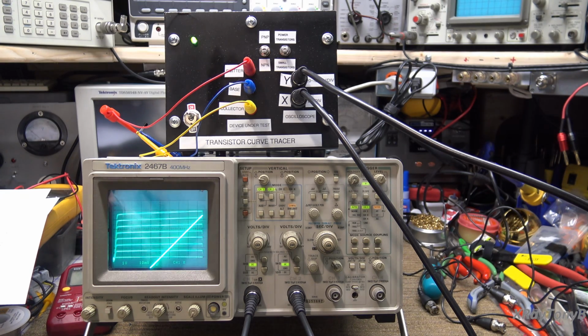And I just took one of those 2N2222 transistors from a previous video that I did on differential amplifiers and thought we would just play around and look at some of the effects that we have to account for when working with bipolar junction transistors and semiconductors in general. Specifically with these transistors, the reason we use a curve tracer is to be able to see how the transistor operates through various voltages and base currents and so forth.